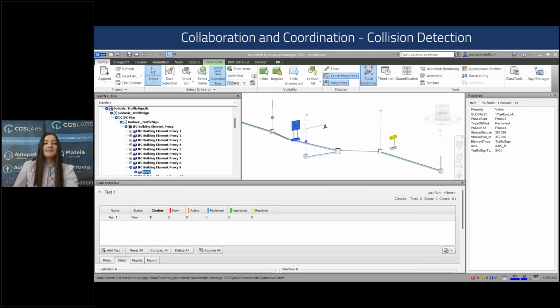Then fortunately, these issues have been solved by the BIM collaboration format standard. It offers a straightforward and transparent way to share clash reports and comments among all project participants. Each problem is assigned a unique ID, making it easy to monitor the number of open issues, responsible parties, and deadlines for resolutions. This means that users no longer need to spend time hunting for issues within the model, because with the BIM collaboration format, they can instantly pinpoint their location.